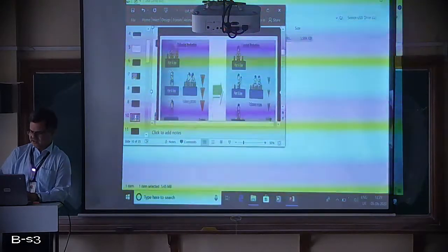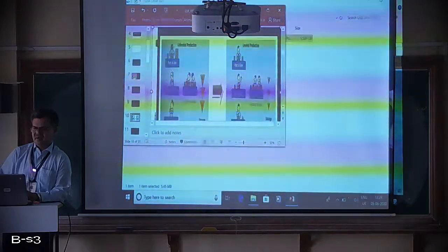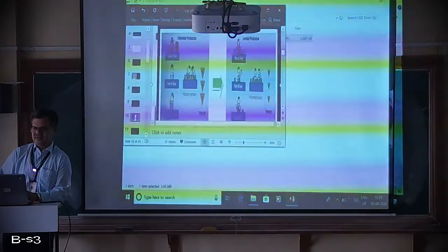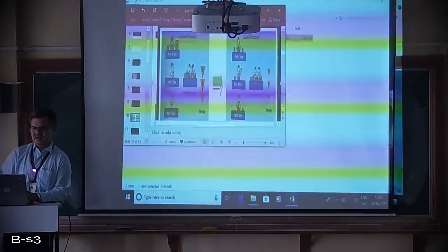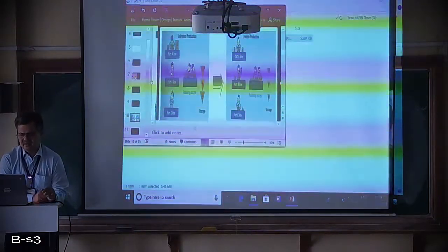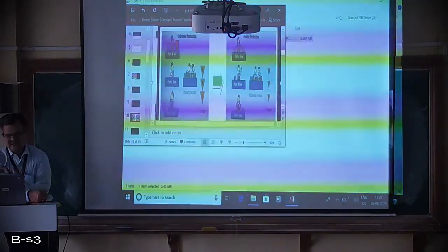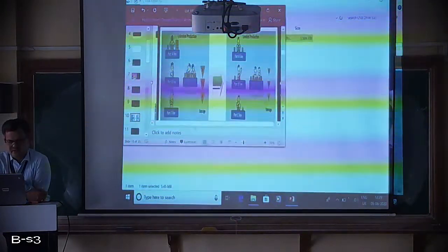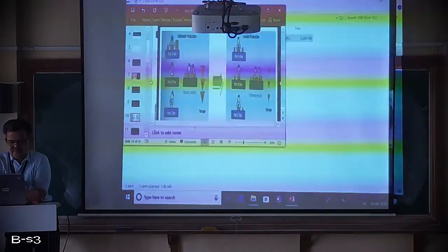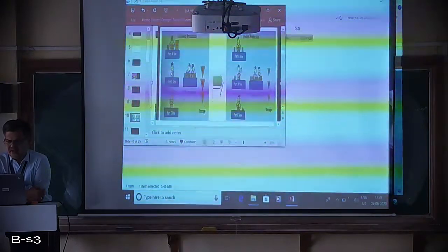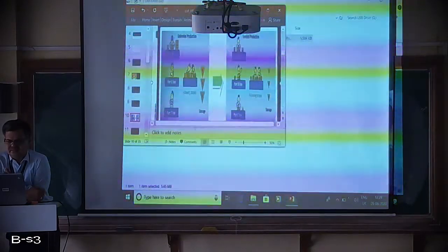Yeah, you can see it. What happens in level production and unlevel production? You can see the unlevel production: part A line and part B line are free, nothing loaded, whereas in the following process you can see one is overloaded and part C line is empty, no work is assigned. So you can say here it is leveled production.